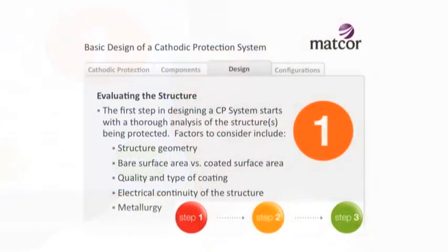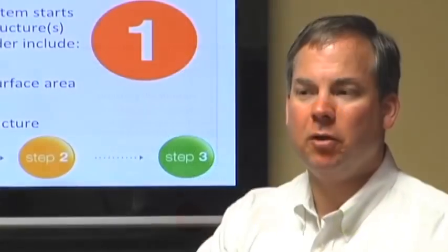That can be a really bad issue when you start putting cathodic protection on it, because you polarize one segment, but current's not flowing to the segment that's isolated because it's not part of the circuit. Now all of a sudden you have a major opportunity for current to flow onto the structure that's isolated and then back off again because it has to get back to the circuit. And where it goes back off, you can have corrosion. We call that interference. And you can actually cause corrosion very quickly if you do that.